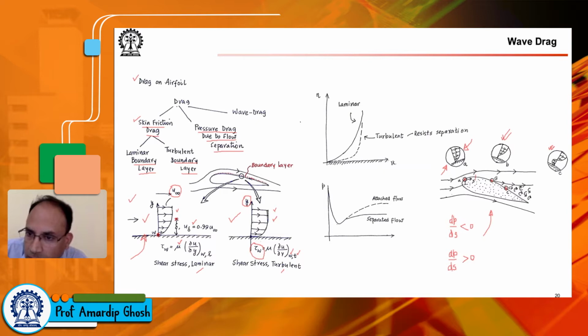So you see that the boundary layer actually separates, and in this region we have something that we have talked about before. We say this is the separated region, and the pressure in this region is almost uniform, and often it is the same as the pressure at the point where that separation is happening. So how does that contribute to this drag? Okay, how does it cause the pressure drag?